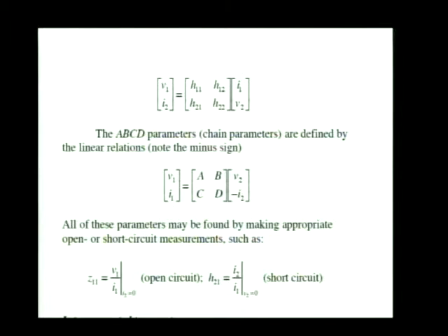Well, here it is. That's the mathematical expression giving a linear relationship between I1 and V2 and V1 and I2. There we go. And the coefficients in that linear relationship, those are the H parameters, the hybrid parameters. And that matrix in this equation, that's the H parameter matrix. Those are the hybrid parameters that are typically used for electronics, used for transistor circuit analysis and design.